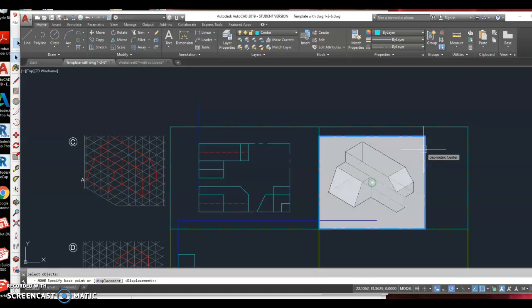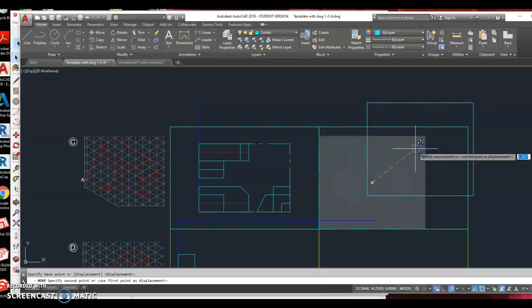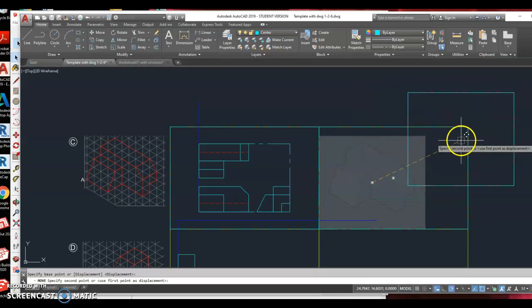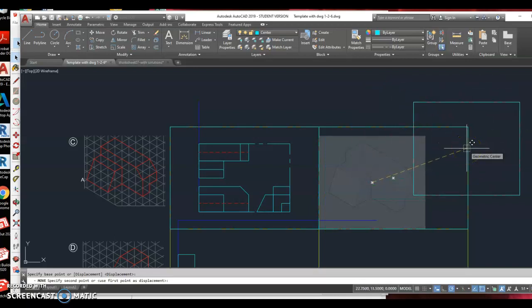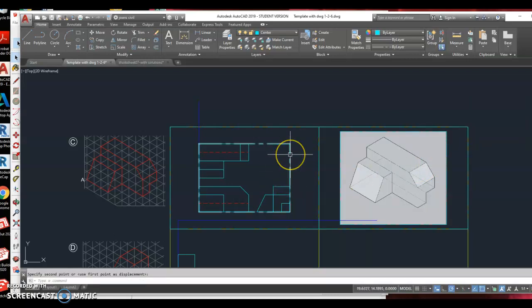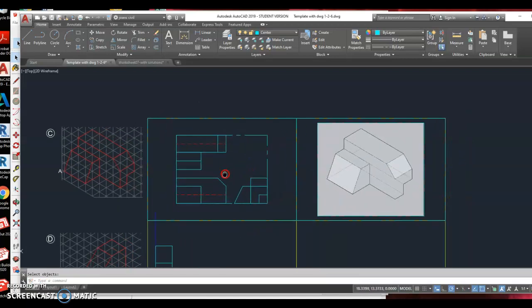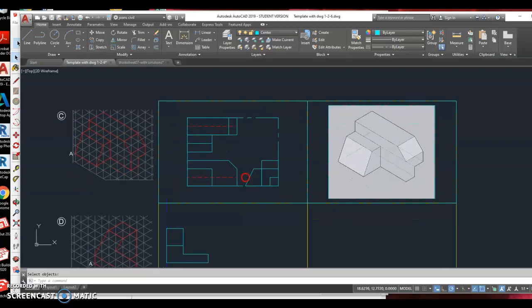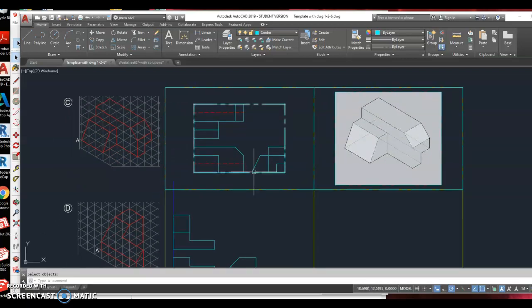You can see the circle with the asterisk, clicking. And then I'm hovering over the outer rectangle on the frame, and you can see its geometric snap is now highlighted, so I can snap. And so I've moved it, and you've got a few little things to straighten up. We have to get rid of these. So that's how you move the 2D graphics into the AutoCAD drawing.